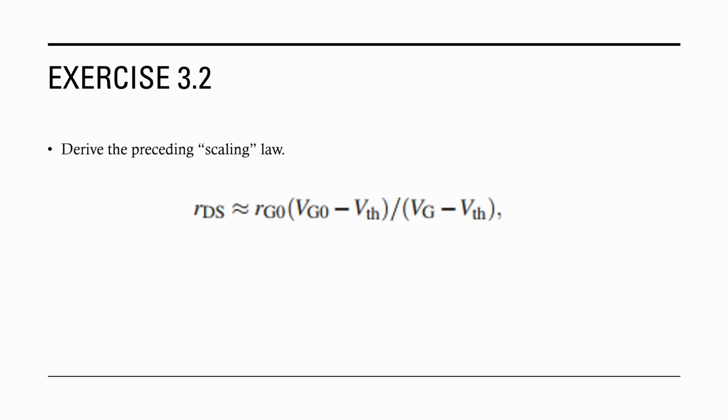By working through the square law relationship, you learn where transconductance and output resistance come from. They're just slopes on the same curve, and I think that's why this question is important and you should aim to understand it as well as you can.